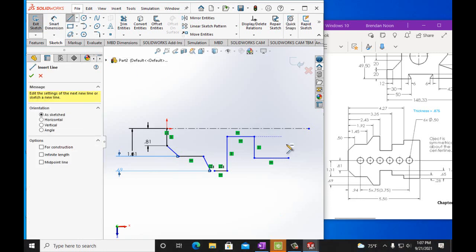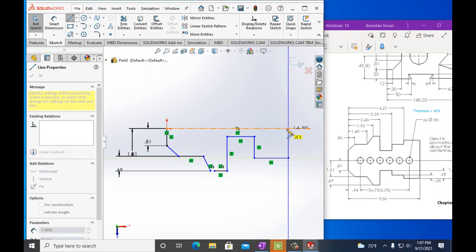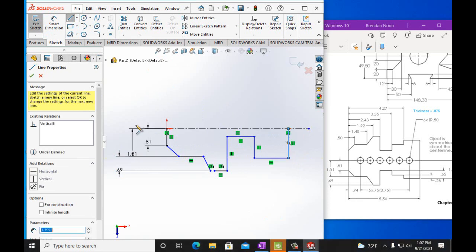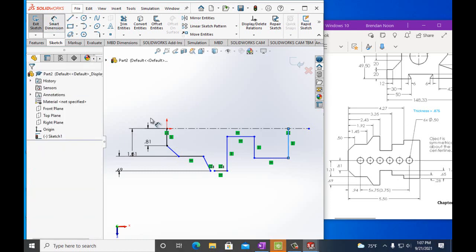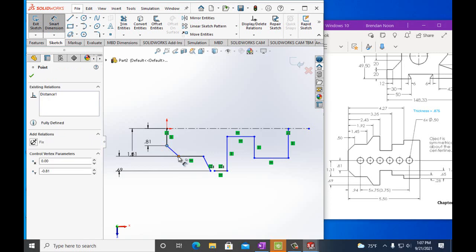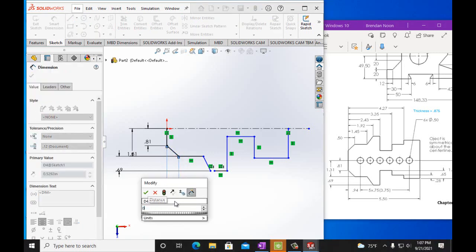All right, draw a line here. Draw this line up to our center line, make it straight. All right, so these are even across. Oh, I see there's measurements up here. They're symmetrical, the measurements down there. Okay, so we go back to smart dimensioning this. All right, so here to here, which is these points, is 0.5. So from here to here is 0.5 inches.